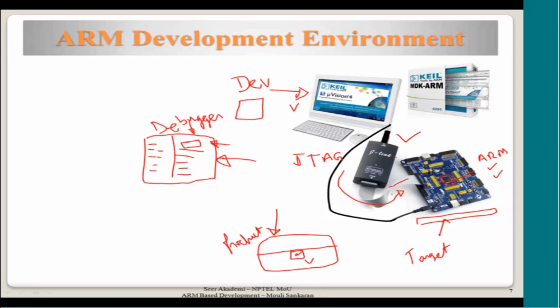Then run a lot of test cases, not a few test cases but a set of test cases, to make sure that you generate different scenarios, different inputs, interrupts or timing scenarios, and verify that the software is meeting all the requirements and is very stable and reliable on the development platform, and then take it to the final target platform.